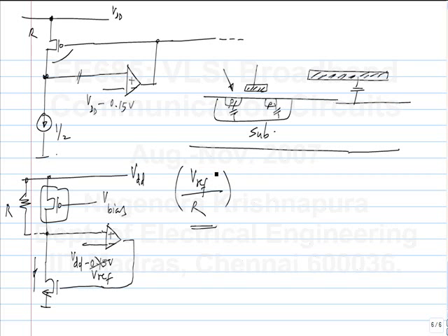I think you already know. Of course, you can bias with constant currents, or you can make circuits where the gm of the circuit is a constant. Are you familiar with that? So if you're not, we can deal with it sometime later. But it's also some kind of feedback circuit where the currents adjust themselves so that the gm will be equal to the reciprocal of some resistance or some reference conductance.